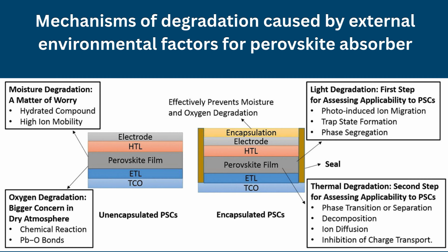Environmental and operational stability. PSCs are highly sensitive to humidity, temperature, and light exposure. Moisture can induce perovskite decomposition, while thermal stress and photodegradation accelerate device failure. Strategies to mitigate these effects include hydrophobic coatings, compositional tuning, and optimized device architectures.